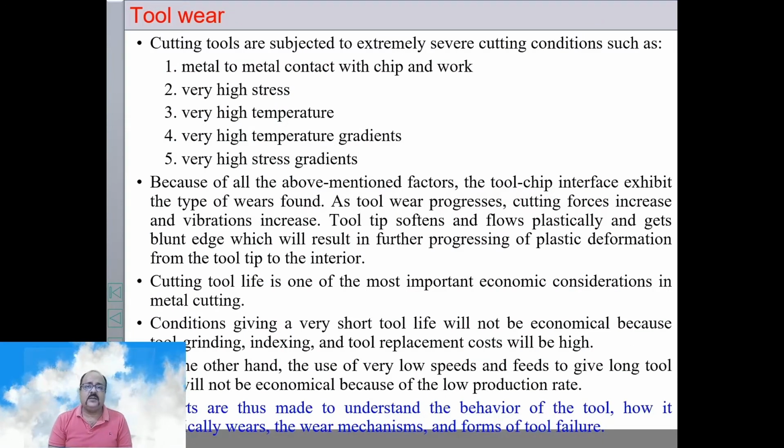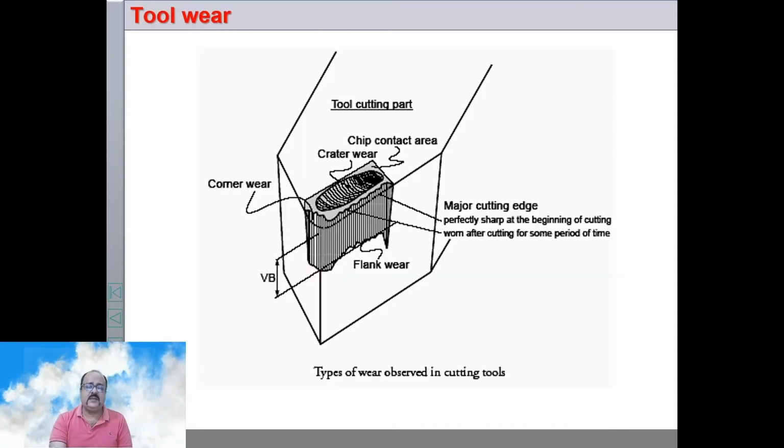It doesn't matter what type of cutting tool material you are using, it will wear. It will wear because there is metal to metal contact between the chip and the work. Very high stress is acting and high temperature. Also there are temperature gradients and stress gradients. So it doesn't matter what type of tool you are using, what type of coating you are using, the tool will wear. And our objective is to extend the life as much as possible or to reduce the wear as much as possible. So wear happens because of many reasons, and there are different types of wear.